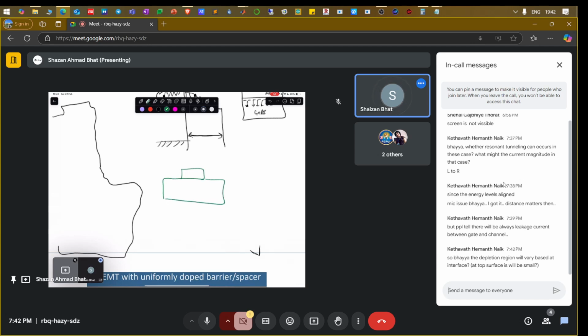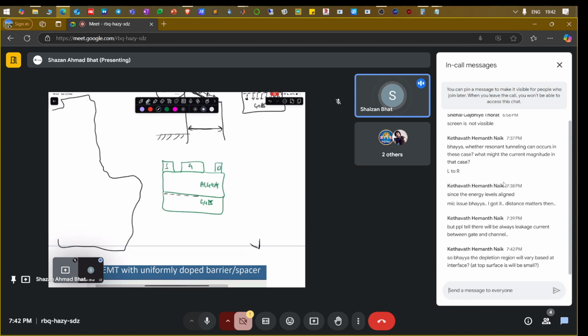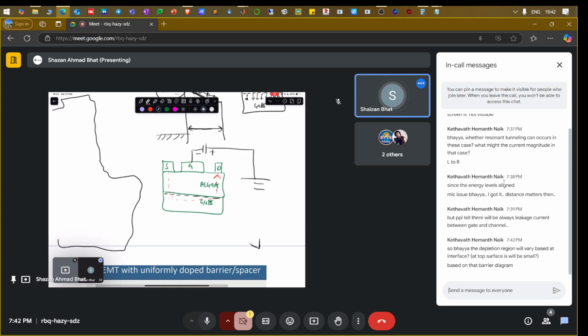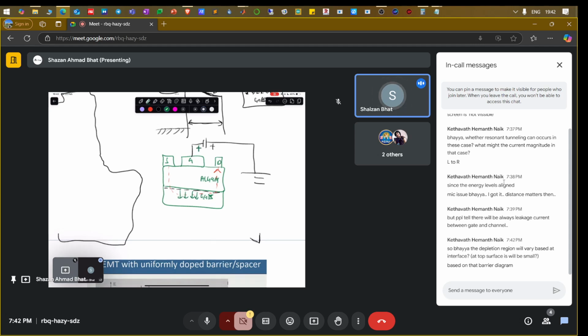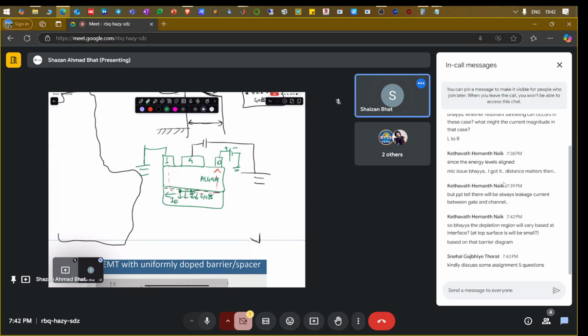If this is a device, this is, let's say, AlGaAs, gate. So you have a source here, drain here. So this is 2D electron gas. So you have the current flowing in this direction, that is modulated by this gate. Negative electric field repels electron, turns it off. Positive field brings it back, or zero field brings it back, and you apply some voltage here. Let's say positive voltage, ground it, and you have the electrons flowing in this direction, current flowing in this direction, which is the drain current.